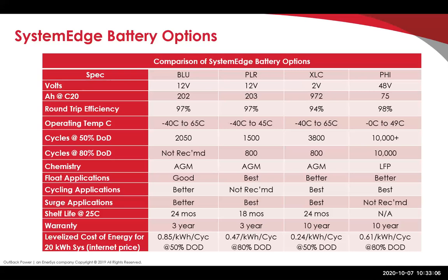Yeah. And another question, and this is sort of as it relates to the levelized cost of energy. Do you have information regarding the capacity degradation over cycle life as that pertains to the overall performance of the batteries? Yeah, the deeper you discharge, the fewer cycles. The other really important factor in battery life is temperature, right? When you are charging and discharging a battery at high temperatures, that definitely has an impact on the battery. Probably as much or nearly as much as the depth of discharge.